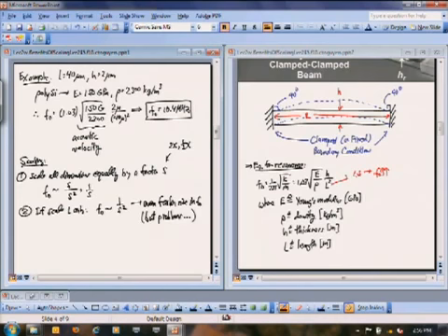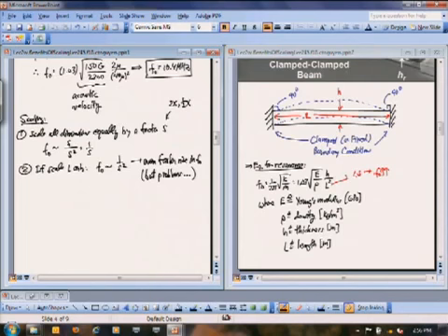But before doing that, let's put one more example down here. I'll keep that equation up on that side here. And basically, I want to find out what it takes to get to a gigahertz. I guess I'll just tell you right now. What it takes to get to a gigahertz is to make your length not 40 microns, but 4 microns. So if you scale that length by 10 times down to 4 microns, keep all the other dimensions the same way, and ignore width effects.